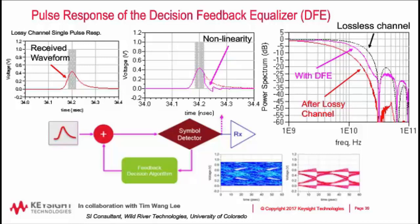And with the decision feedback equalizer, we see very quickly that it does not do anything to the rising edge. It's a slicer type of correction where at each transition it knows what bit it had just received, and it's slicing to correct for that falling edge, or I should say the slow tail sort of transition there of that bit. So the decision feedback equalizer really only helps us on that falling edge here.